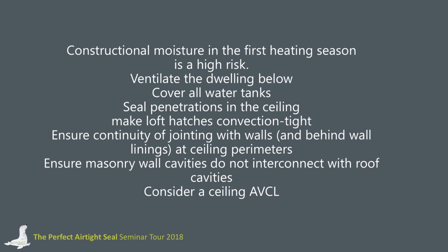One of the big issues is if you have loads of constructional moisture in your building and you're in the middle of a first heating season, the amount of moisture that can get into a loft space is very substantial, and you might get condensation even if you have ventilation. So it's important that the dwelling below these ceilings is ventilated, water tanks are covered, and in particular the penetrations into the ceiling are all sealed. Loft hatches are a major source of heat loss and moisture ingress, and we saw earlier today how a small gap can allow a lot of moisture to escape.